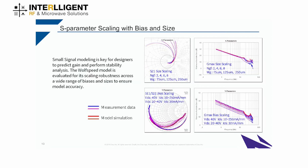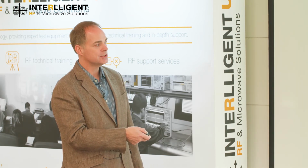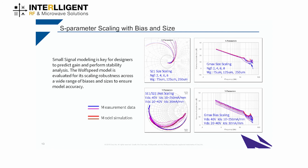And then similarly with both size and bias, we want to make sure that the S parameters are properly following the performance of the device. And we can see here from the Smith charts and the MSG charts that we are getting very good correlation over both a range of biases, where we're ranging it from 20 to 40 volts, and then from 10 to 250 milliamps per millimeter bias conditions, and over a range of device sizes at a given bias condition.